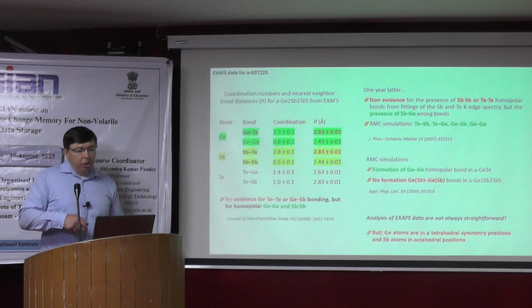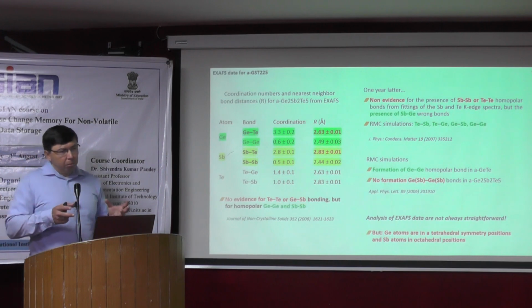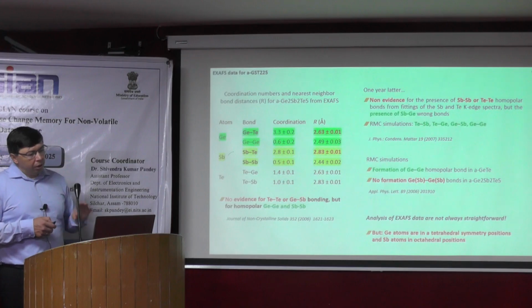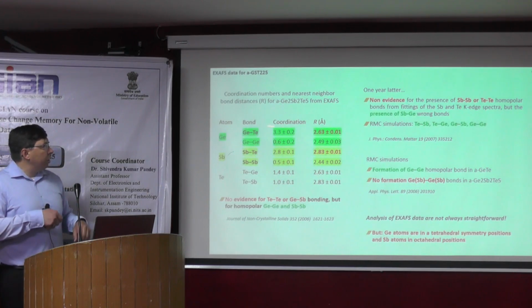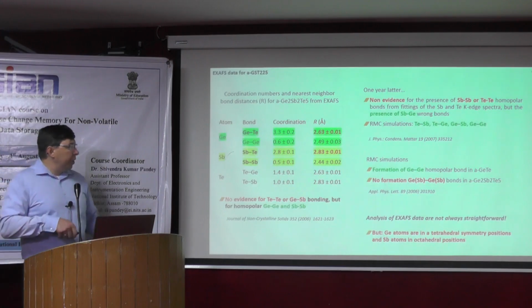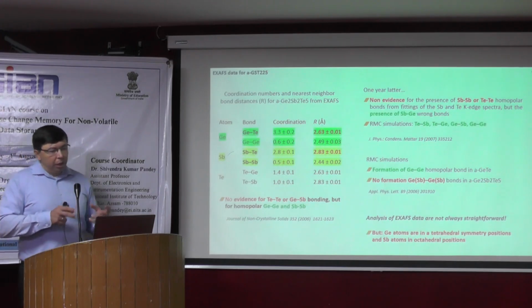Why is it so important? It's very important to understand the switching mechanism in amorphous phase change materials, and we will study it, I think, tomorrow in the phase change mechanism lecture. So please remember here that from the XAFS study we found that germanium is located in tetrahedral and antimony is mainly in octahedral positions. And octahedral is also the main structural motif of the crystalline phase.